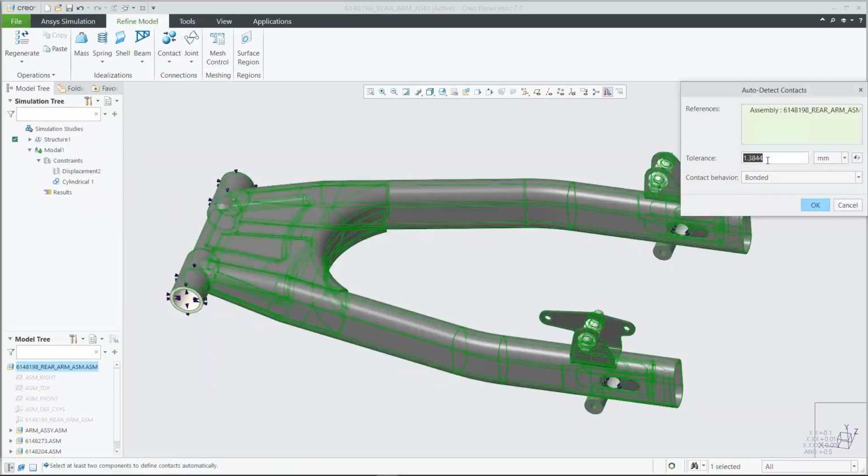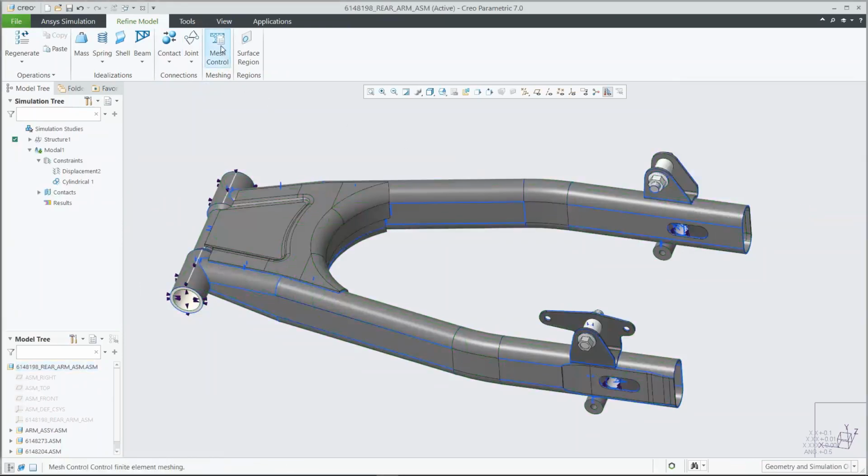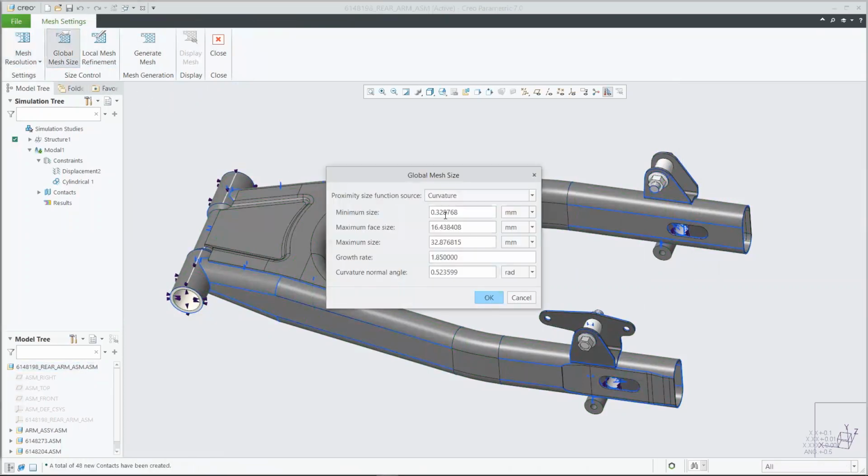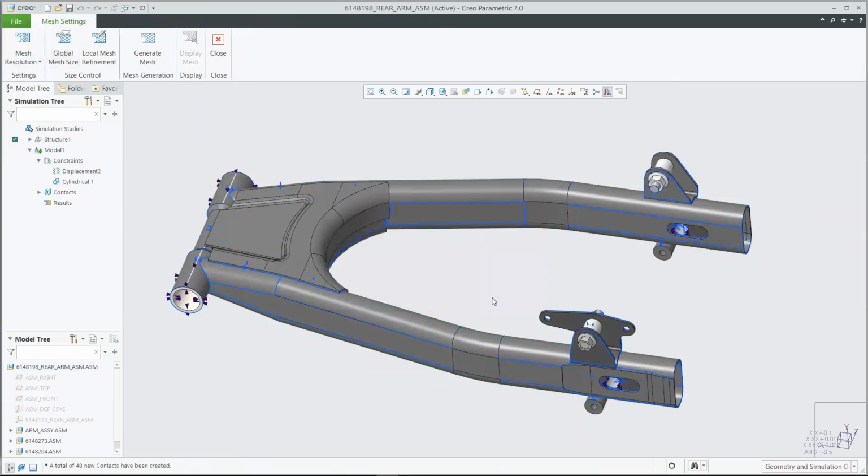Go ahead and lay that out here. All right, and then we'll go ahead and set up the mesh for the study. And again, the workflow is pretty much the same up until this point. If we wanted to get more of a higher fidelity run, we could go through and have a little bit more control over the specific size of that here. And now we'll go ahead and generate the mesh that we laid out. And overall, fairly quick to run through and do.